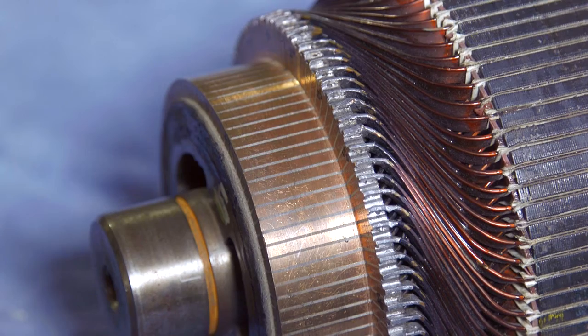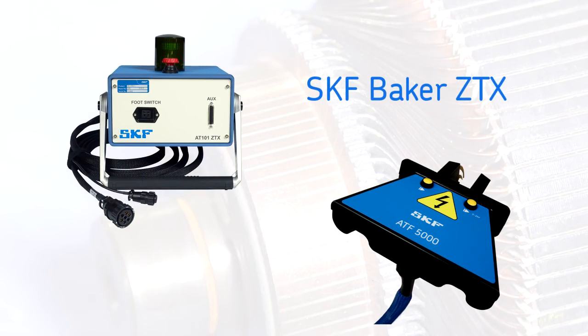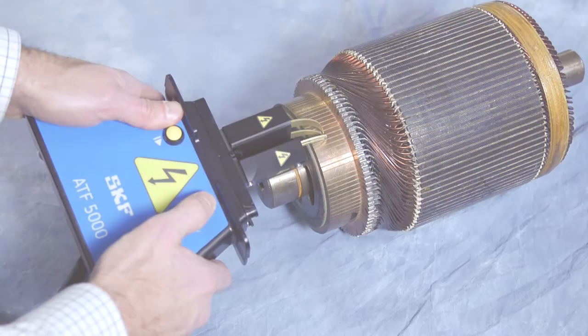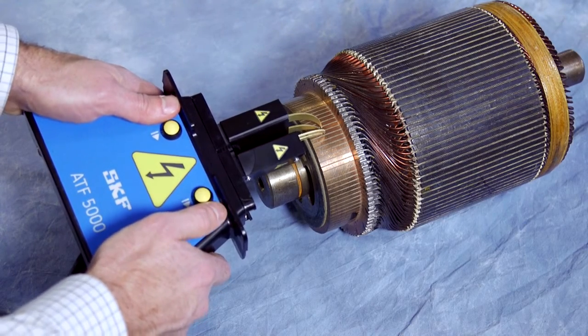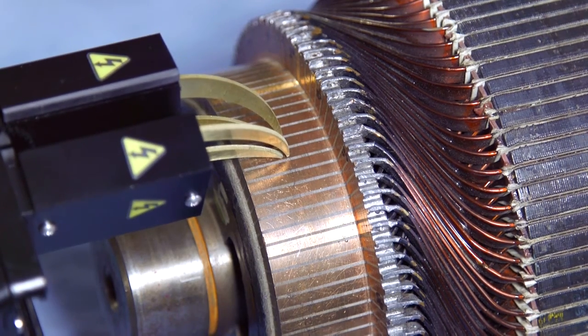DC motor armatures can also be tested using an SKF Baker's ZTX adapter with an SKF static motor analyzer. The ZTX lowers the surge voltage while increasing the current. This allows bar-to-bar testing of the armature with excellent fault location.